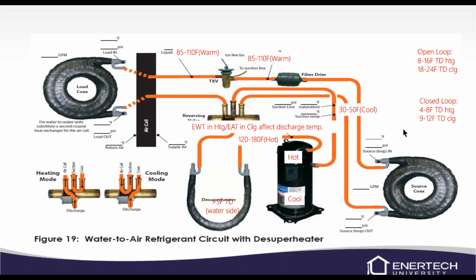I'm sorry, I think I messed up on that. The more flow you have, the less temperature difference. It's not in contact with the pipe as long, so it can't transfer as much heat. The top of the compressor should be hot. The bottom should be cool. If you see frosting and stuff, that's usually a sign of possible overcharge down here at the bottom.